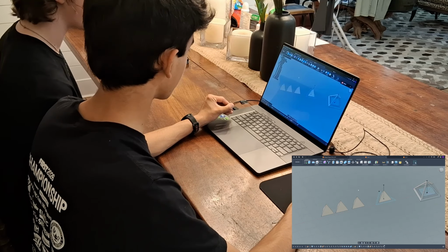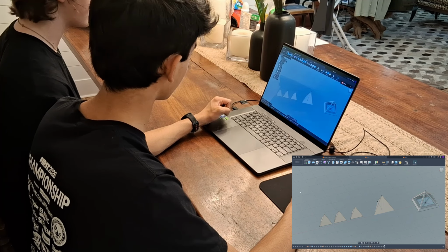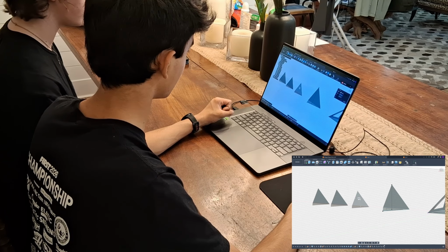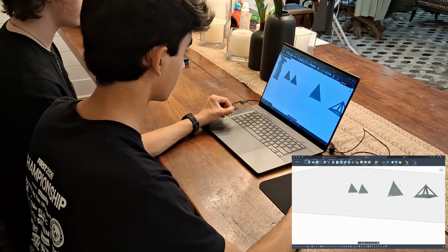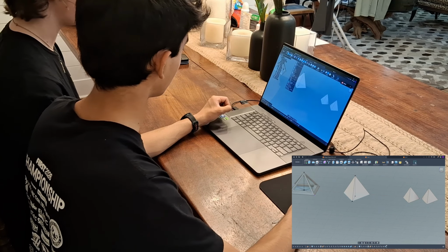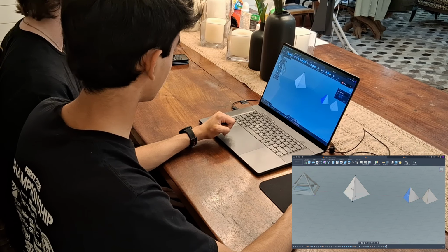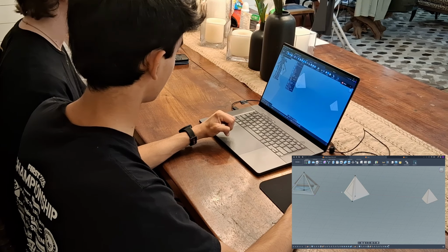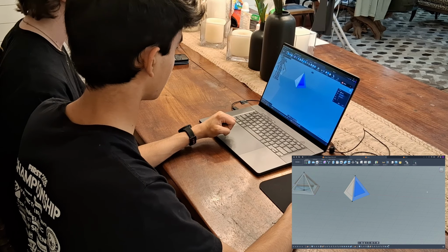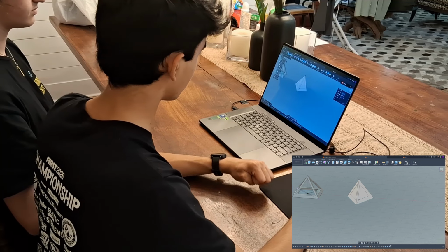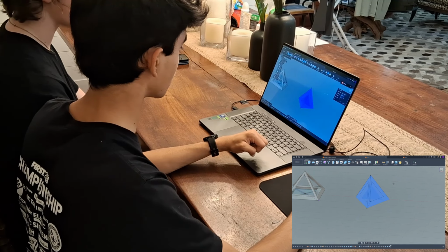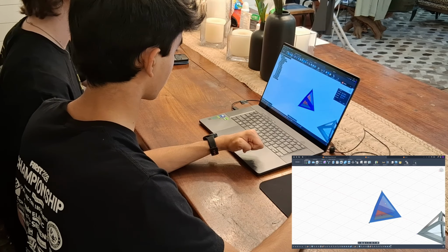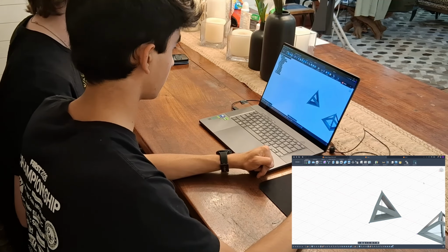Okay, so now we're gonna come back and make sure we show that shape again, and then we're just gonna do our lines again. So we're gonna go to modify, make sure you select that face, match the face over here. Same thing for the other 2 sides. So make sure you align it right there and right there. And then I'm just gonna go ahead and also do the combine. So make sure you select your target body as the large pyramid, tool bodies as the small ones, and then after we're gonna do our cutout. So make sure it's selected on the cut operation, and there you go.